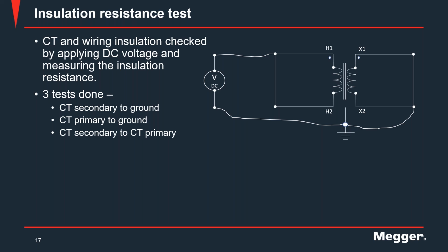When you do the integral of that voltage, you get a calculation of the flux that is produced, and when you do that, you can get the saturation curve. So that's why, by applying voltage, you can get to that point. Now, when you apply an AC voltage, you are increasing voltage gradually.